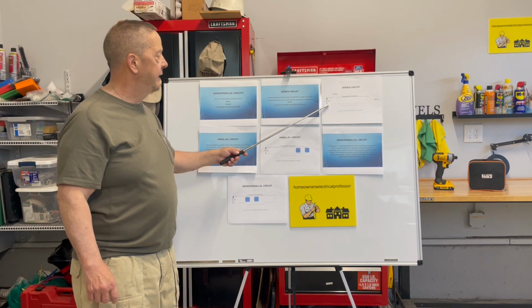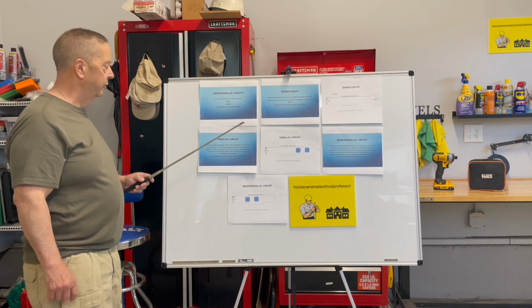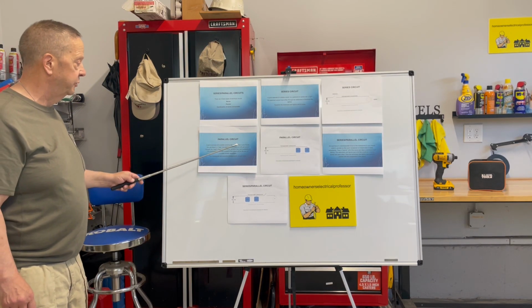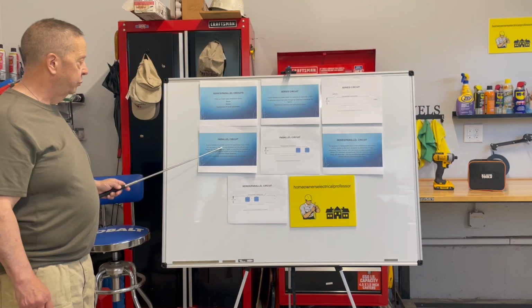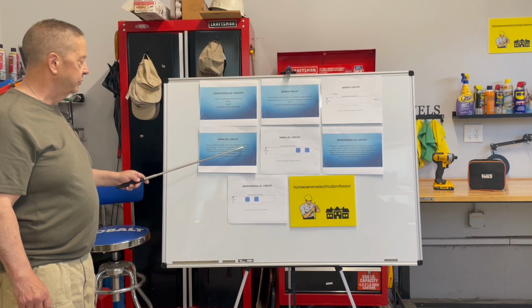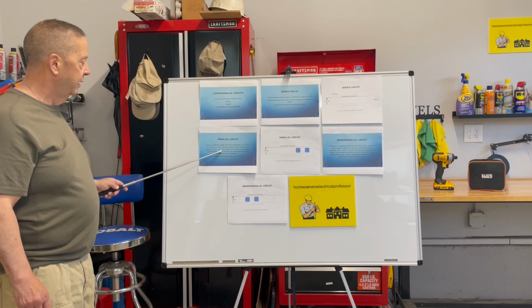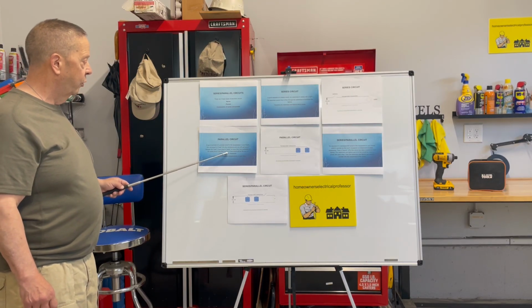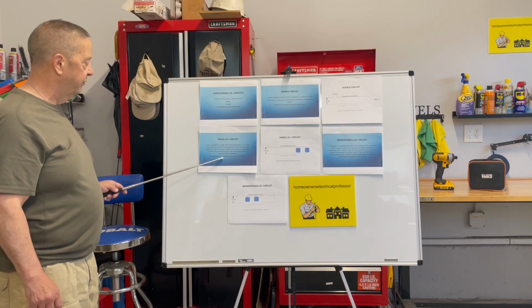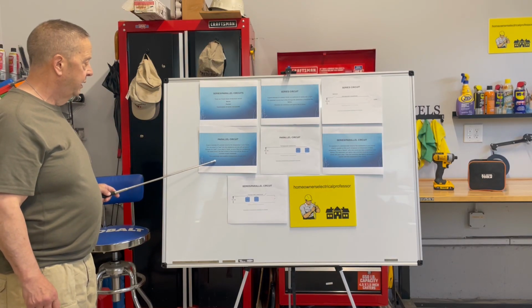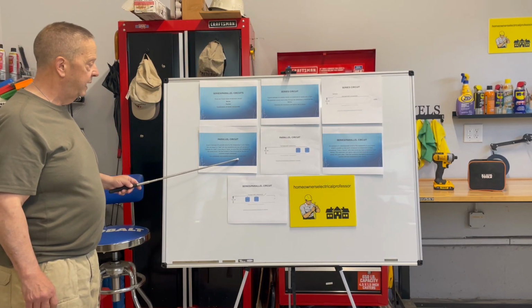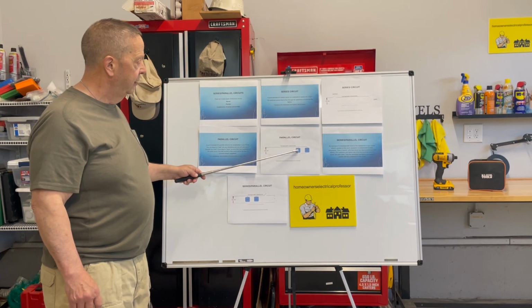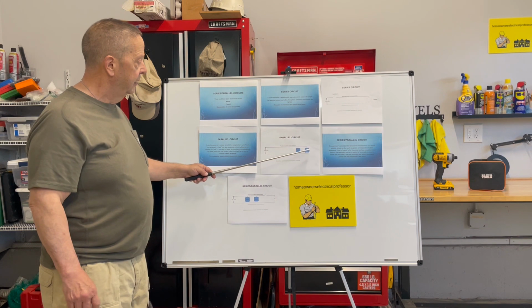A parallel circuit, a good example of a parallel circuit is receptacles in your house. You can plug a load into any receptacle and you will get current through the load. If you plug in loads at more than one receptacle in the same circuit, the total current in that circuit will be the sum of currents at each receptacle. The receptacles are available independently of each other. Here's your 120 volts, here's your hot wire. It feeds both receptacles, and then both receptacles have a return path through the neutral.